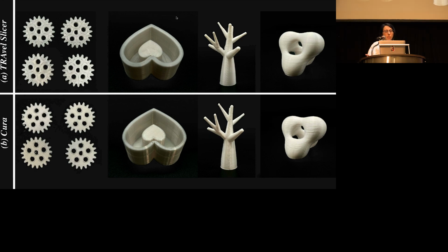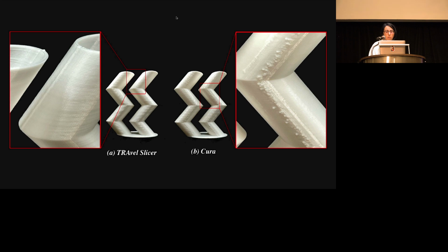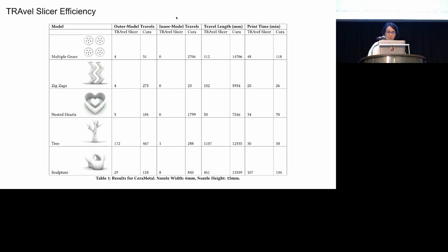The quality of the PLA prints was comparable when sliced by Travel Slicer to prints produced by Cura, but in some cases it was better. The seam was neater as a result of fewer movements back and forth between the zigzagging pillars in this version.